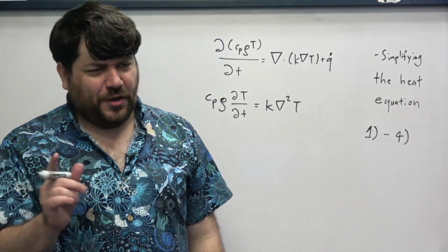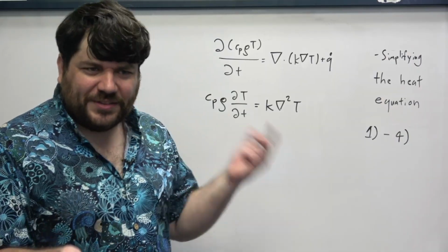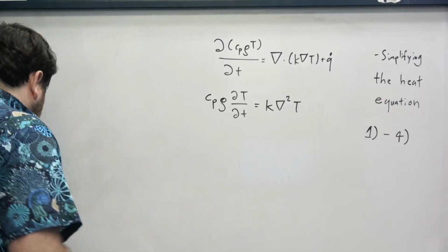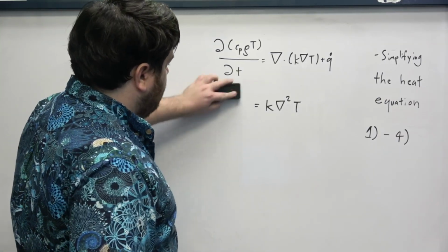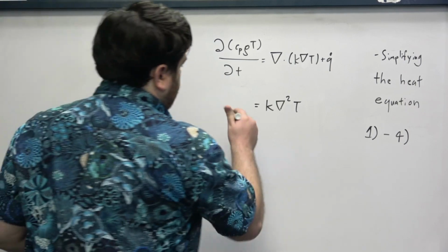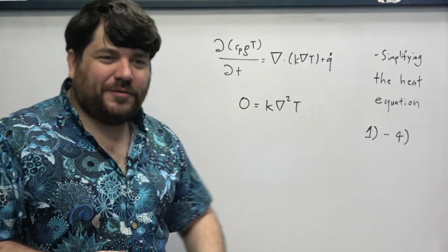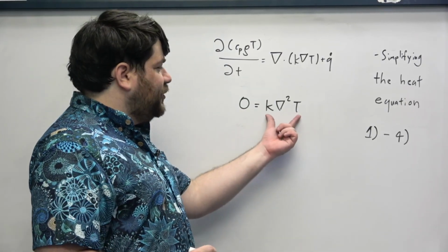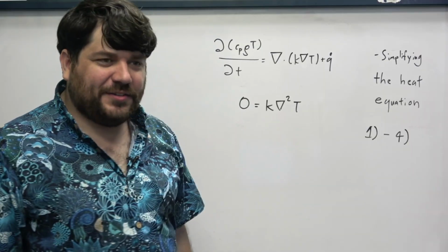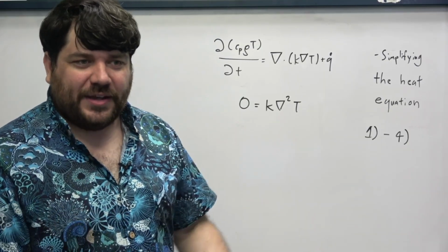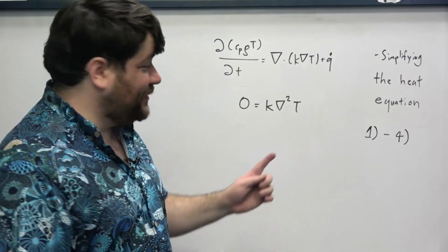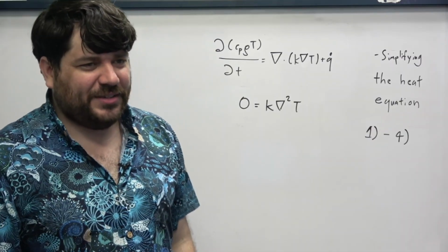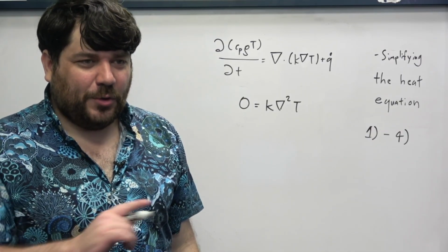Then we make the assumption that the system is in steady state, right? The temperatures don't change over time. Well, if we do that, then this whole term over here goes to zero. And then what if we assume that the heat transfer occurring in the system was one-dimensional? That simplifies this goofy vector calculus expression into something that looks like partial derivatives, right? And because there is no dependence on anything else, because time no longer shows up, those partial derivatives can be substituted with total derivatives.